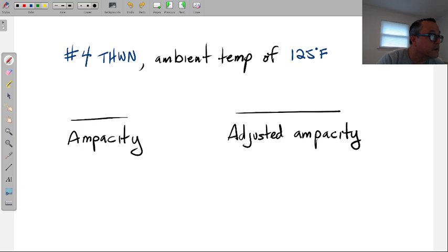I think this is a wire. Yeah, that's a wire. Number 4. And so I'm going to drop that here just to make sure if anyone is stumbling across that, there is your ampacity. So number 4, THWN, which you're probably never going to find anymore unless you go to like an old supply house in some lost city somewhere. 85 amps.